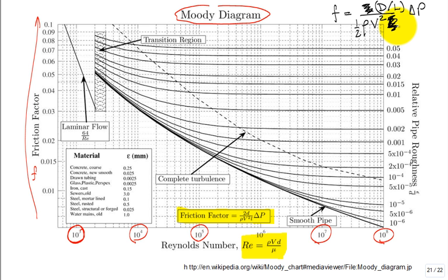Yes, sir. Are all these D's like hydraulic diameter? If it's pipe flow, all of this data is going to be for pipe flow. Then yes. But you will see people use the Moody diagram using the hydraulic diameter for non-circular, and it's fine. You just need to know that that's an additional engineering assumption that that's going to be close. Okay, so this is a friction factor.